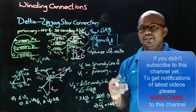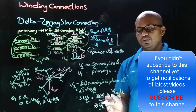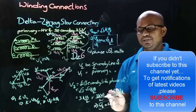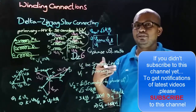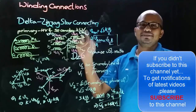And if you consider K is equal to 1, observe that the secondary side line voltage V2 is equal to 1.5 times the primary side line voltage, which will tell you that the secondary side line voltage is 50% more than the primary side line voltage. Means delta zigzag star connection is used for step up applications. Therefore, this is about delta zigzag star connection.